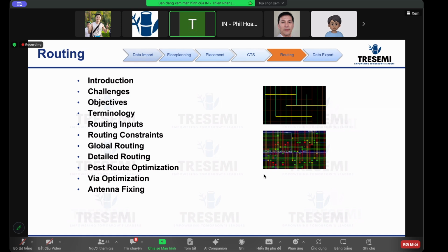And then another thing is global to detail route. I think here is a good point: the signal integrity, the SI, right? So usually by default, when we run global route, we do not consider the SI, because it's just a matter of trade-off. When you do the global route, by nature, it's not a final route, right?